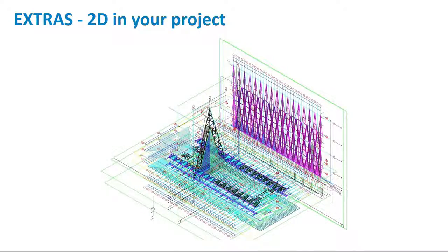That was going to be my sort of parting gift, and then Fernando, who's just turned up, said to me yesterday morning, Desktop Connector has just come out, and that allows you to link DWGs across C4R in a Revit file if you really want to. So there's that workflow as well.